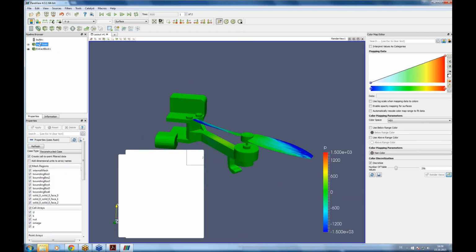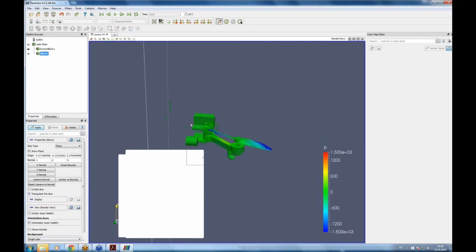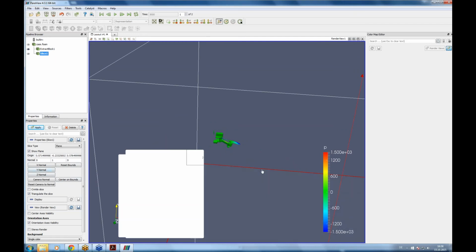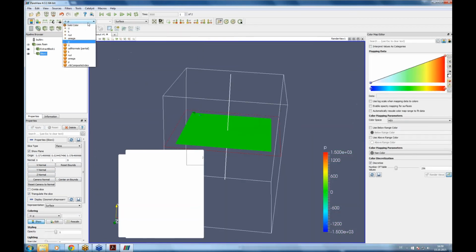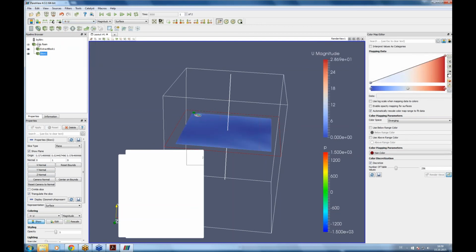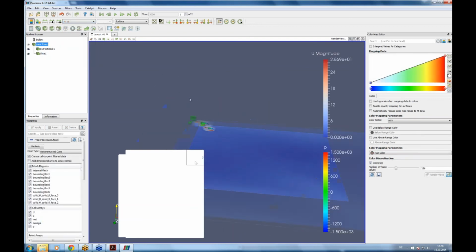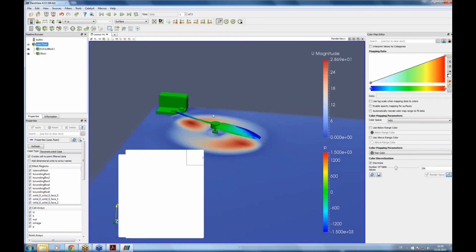You can also do, for example, a cut through the field, through the flow domain. And then here, for example, we can take a look at the flow velocity. And here you can really see how the propeller is working. So here is air, red means high value, is streaming up. And this upstreaming air is accelerated by the propeller, and this creates a lift.